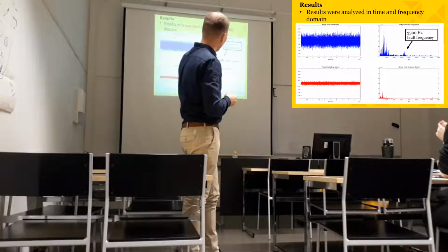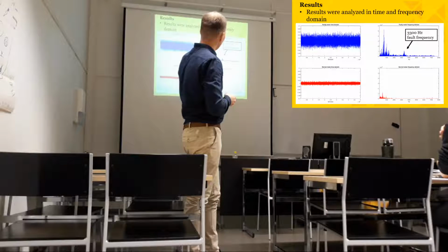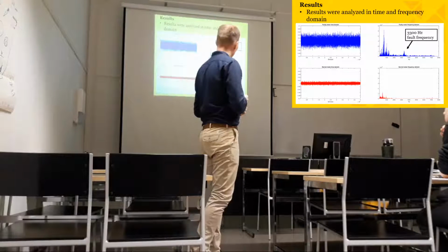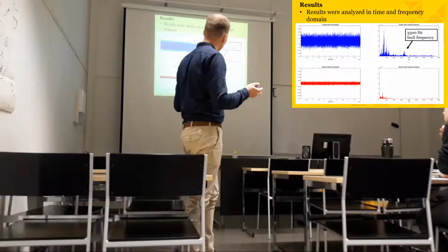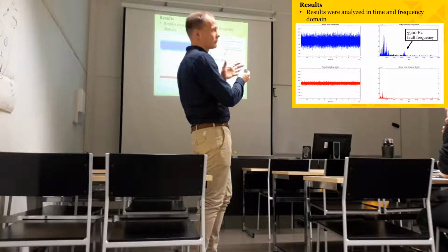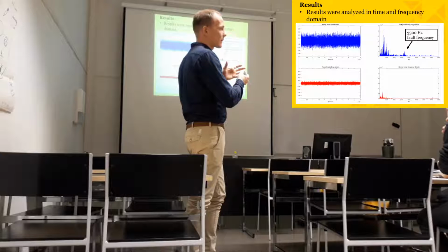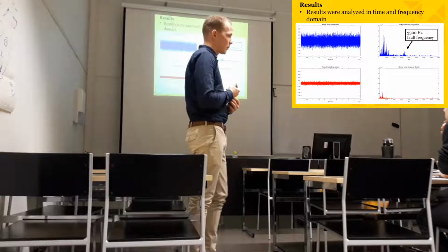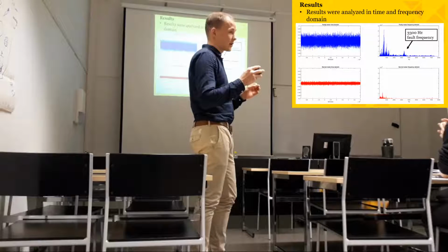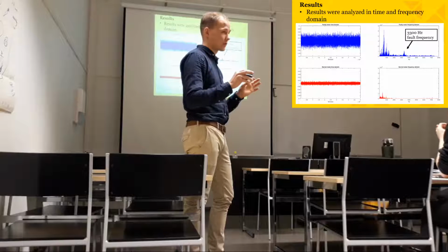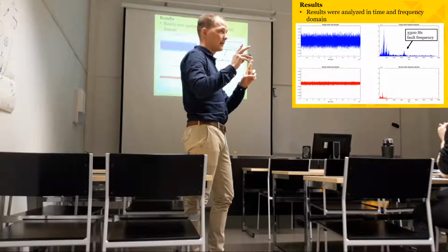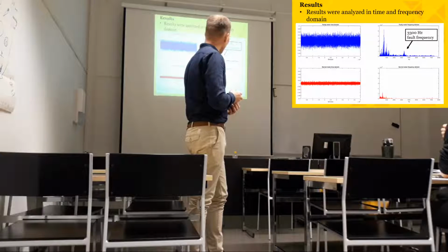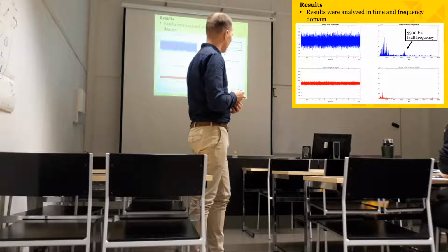If you compare the faulty and normal motor, the frequency spectrum is quite similar, except the amplitude is much higher for the faulty motor, but it also has this fault frequency. In the literature, they also got similar results. They got two of these kinds of extra frequencies popping out from the frequency domain.